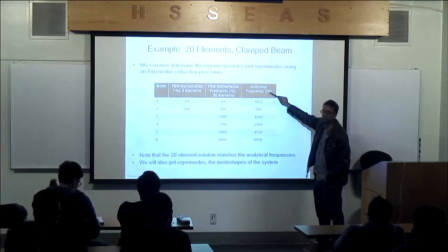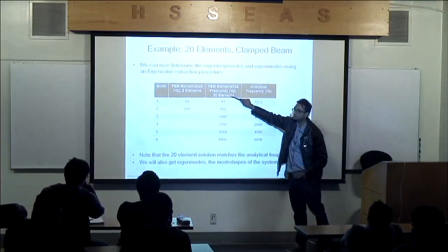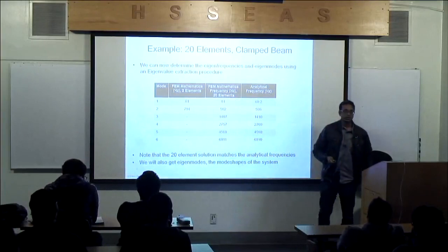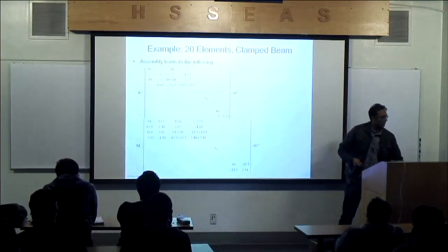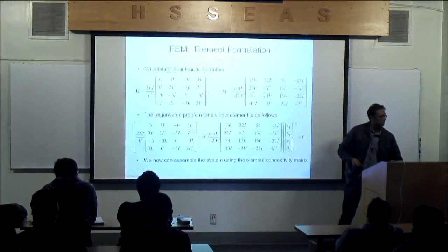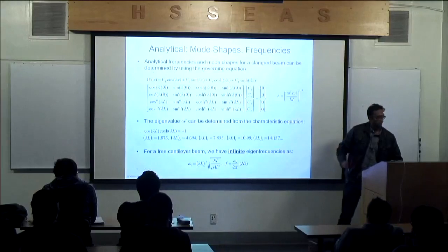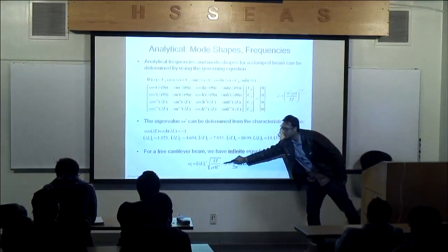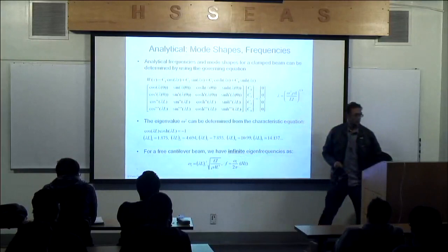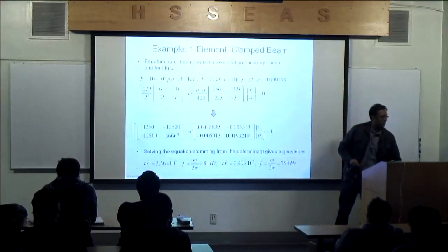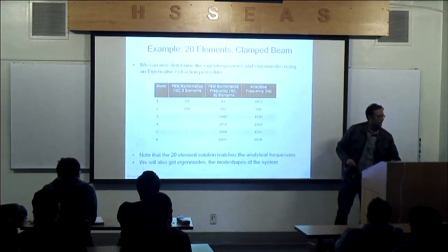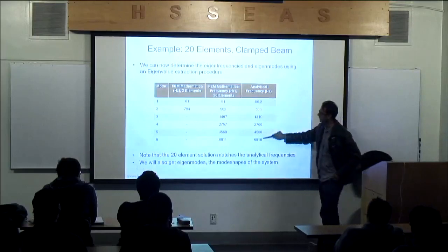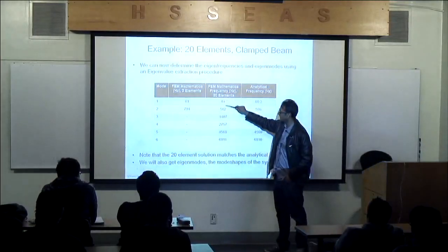Between the analytical solution and finite elements. So, in other words, what I'm comparing here, I'm using this formula right here at the bottom. I'm using that formula for a clamped beam. That's what I'm using. And so, when I use that formula, this is what I'm getting analytically, and then this is what I'm getting with finite elements.